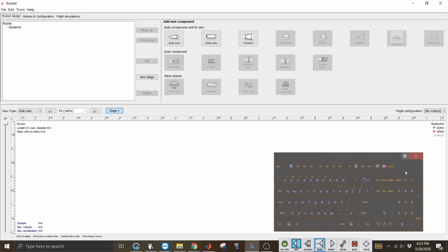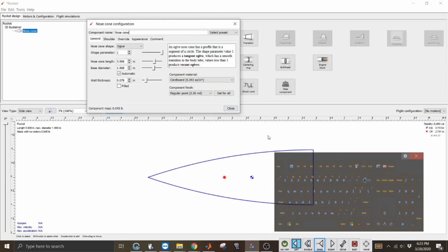Now, I've been designing model rockets for about 4 years now, and my experience at least from what I've worked with, is I like to have a minimum airframe diameter of 4 inches, mainly because it's easier to work with. You can fit your hand in if you're a normal sized person, unless you have gigantic hands. So we're gonna make the base diameter, which is the nose cone diameter, 4 inches.